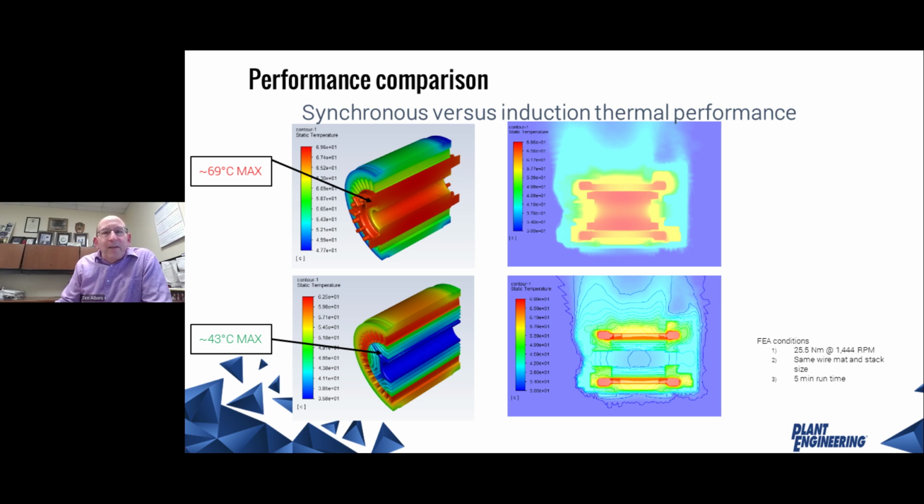One of the big deals here is what gets to your bearing. Your bearing is actually going to get some of the heat from this rotor, and on your synchronous motor, it will not. So it's just one of the incremental advantages of synchronous motors that a lot of people don't take into consideration. I think it's important because it will give you an extended bearing life, and that is still the number one failure mode for electric motors.